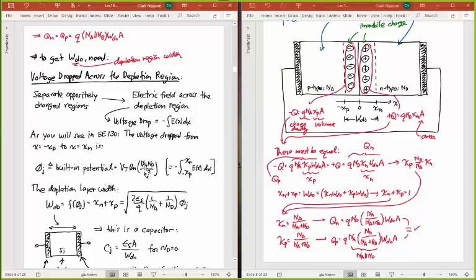That built-in potential, which is basically the potential that prevents those carriers from continuing to move, you can think of it that way, is going to be equal to V_t, which is the thermal voltage we talked about. Remember that was equal to 25 millivolts, times the natural log of the concentrations of dopants on the p side and the n side, N_a times N_d, divided by n_i squared.